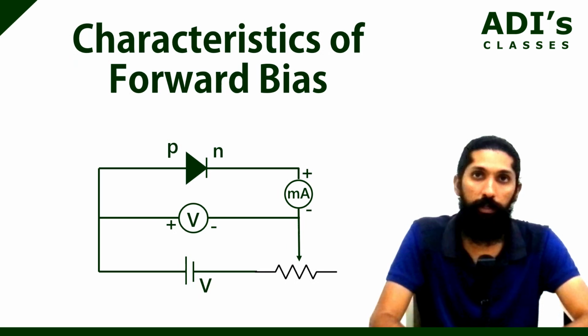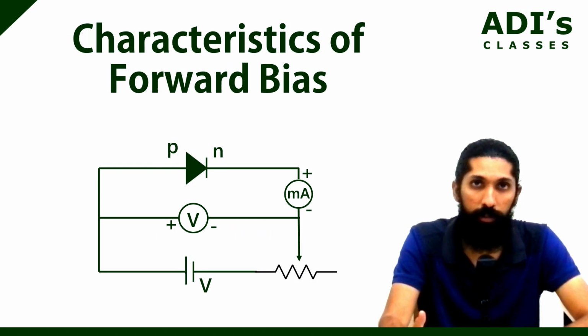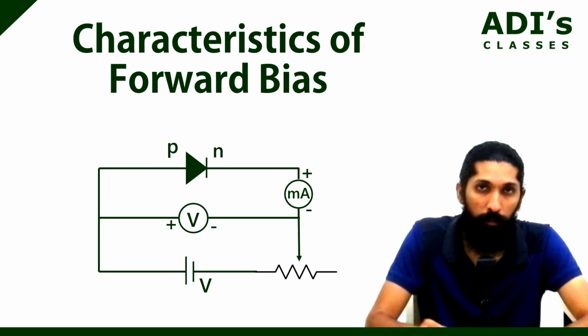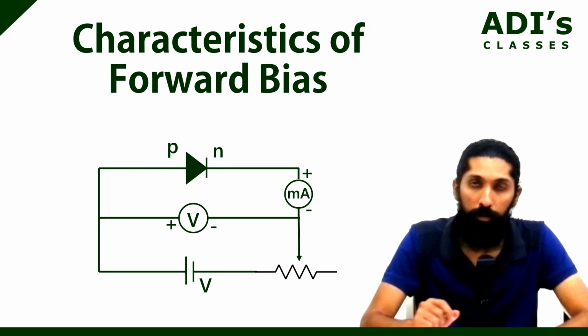What happens in this particular case? First we give one particular voltage. Let's say we are going to give 0.2 volt. Very small. Some current will pass through it and that is measured with the help of the milliammeter. You make a note of it.